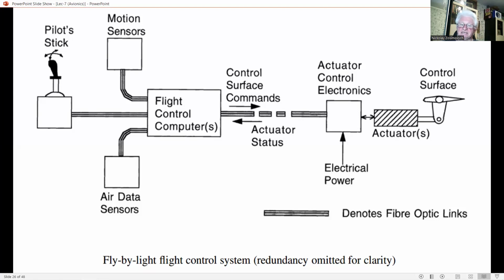Fiber optic links can be bidirectional and can also be used to convey the system status to the pilot's control or display panel. For instance, a wraparound test can be carried out to check that the data have reached their destination, and the status or health of the control surface actuation system can be checked by monitoring the servo error signal and actuator hydraulic pressure.